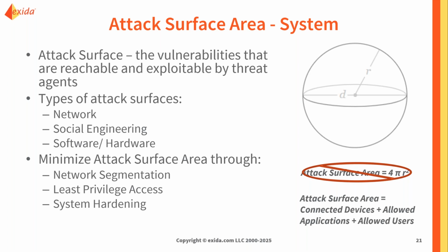We can look at the social engineering aspects. So how many user accounts are we developing? And are we following least privilege and making sure that operator accounts can only view and change set points, that a limited number of engineering accounts are in place and that those are required to make configuration changes? Are we separating control and safety accounts?